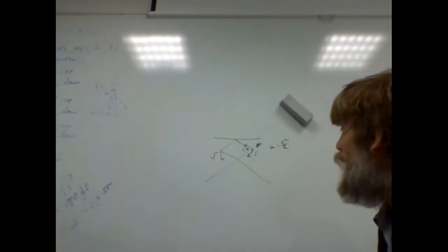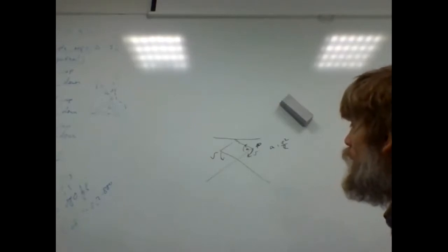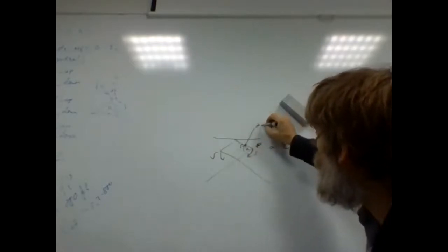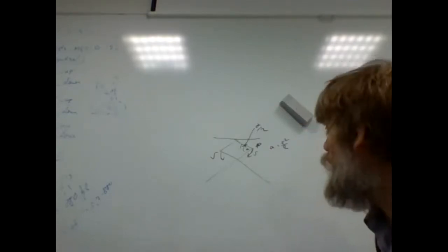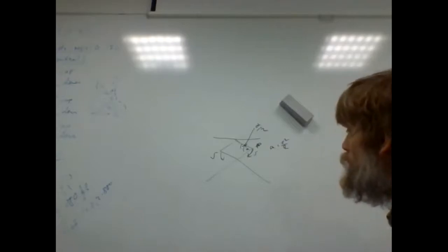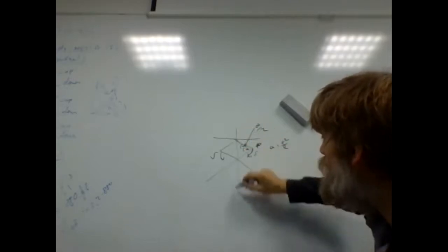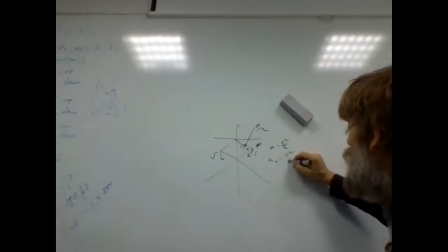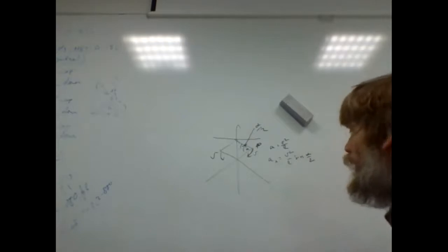And it is at the angle alpha with respect to the bars, between these two bars, which means the angle here is alpha over 2. So if we project now the acceleration of point P to the vertical axis, then we see that AX equals v squared divided by L multiplied by sine of alpha over 2. Okay?